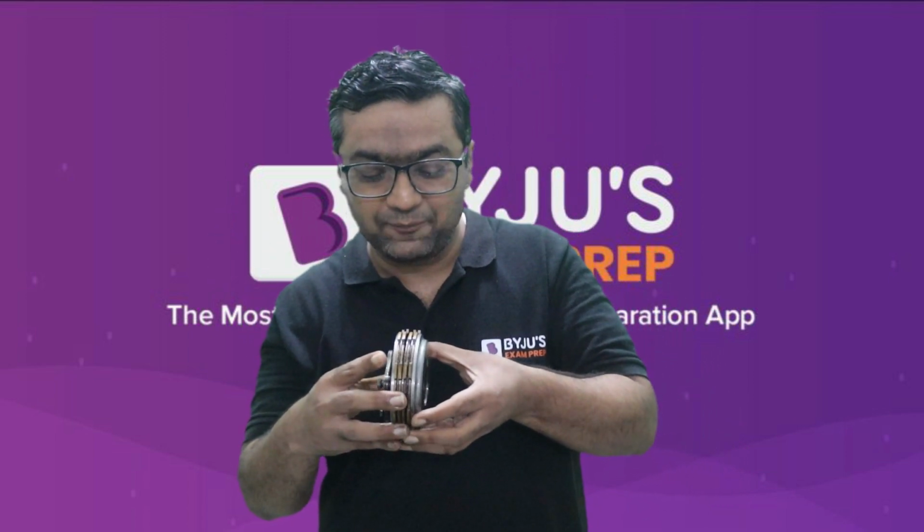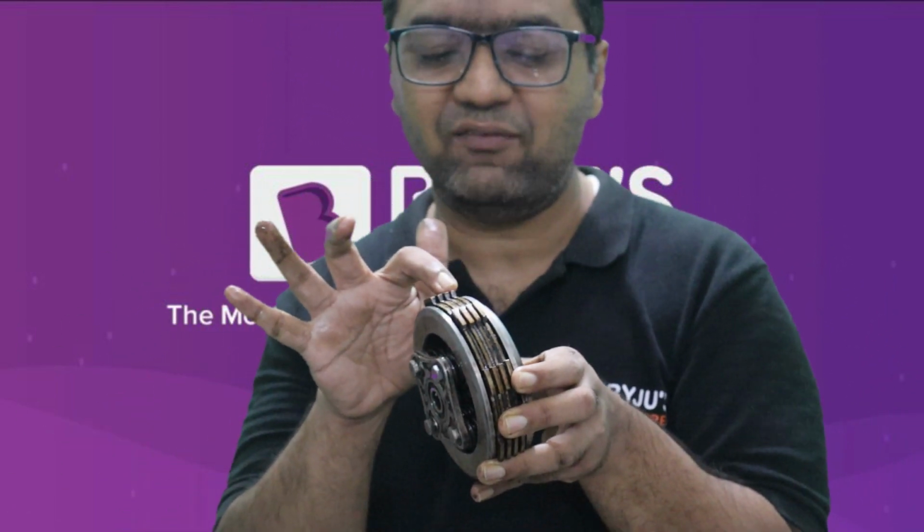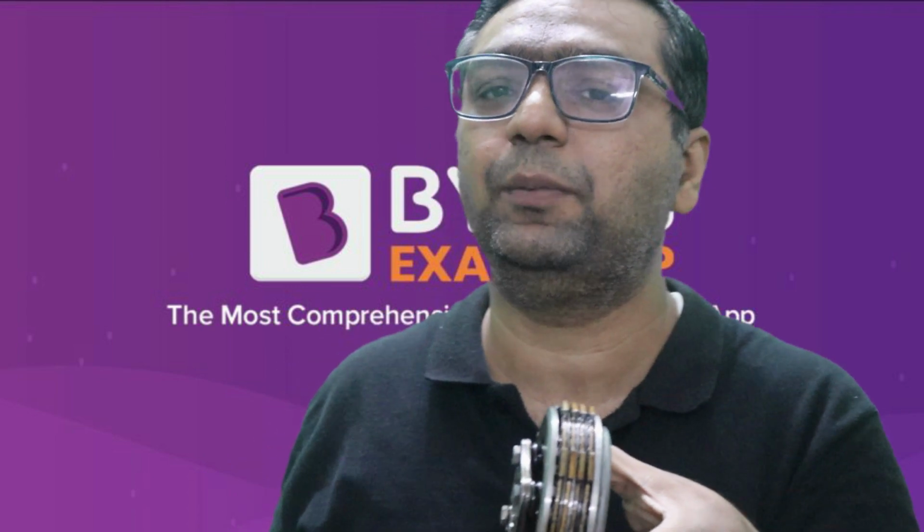So guys, here you will be able to see these are the plates. You can see alternate plates are there. There are some plates which have projections outside, and in between you will see the gap. Can you feel it? All the plates which have projections are the friction plates, the plates on which friction surfaces are there. And in between we have the steel plates. If I count here, you can see 1, 2, 3, 4 friction plates, and in between 1, 2, 3. Total 3 plus 4, 7 plates. So 3 steel plates and 4 friction plates are there.